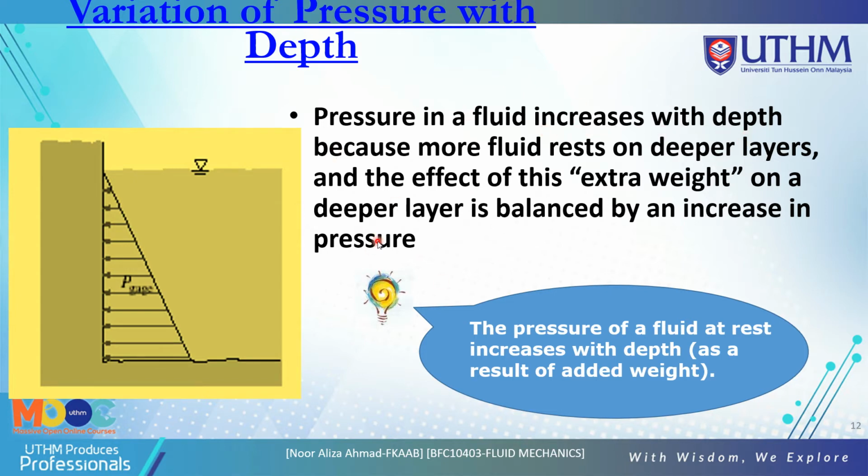In case your test or your final asks you to explain about pressure, you can sketch this figure and explain that pressure in a fluid will increase with depth because more fluid rests on deeper layers. The effect of this extra weight on a deeper layer, from the water here, with the variation of depth, is that the deeper layer is balanced by an increase in pressure.